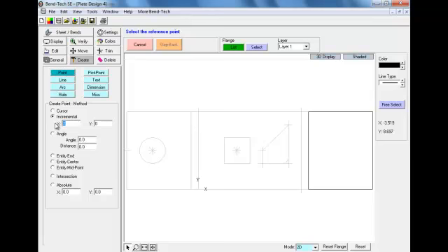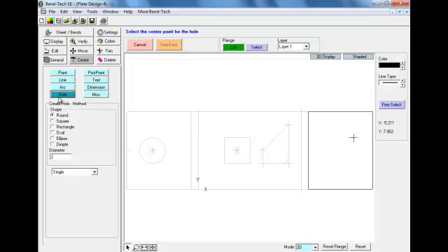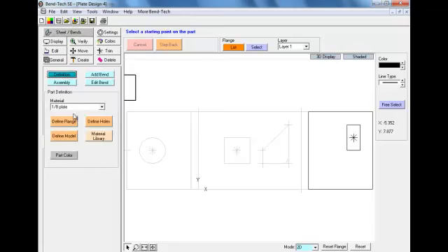We're now going to move over to our right flange. And we're going to select a rectangular hole in that flange. So we need to start out by creating a point. We're going to select the far right corner and drop down our new point. We can then create a hole.